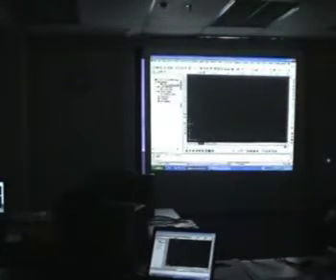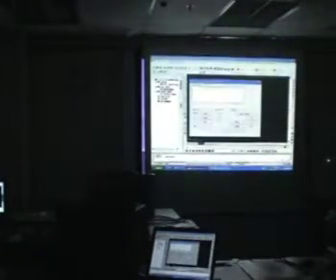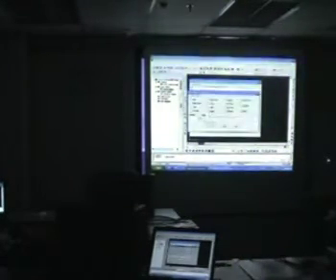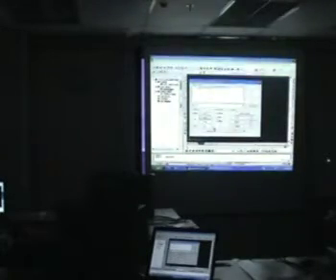And what I'm going to do is extract information from that drawing, because it's possible that drawing may have a lot of other garbage inside. Maybe you've got other contour lines, even other text like the words sekolah, rumah, that you don't want to put into your 3D points. So this is the use of query. We're going to use the current query. This is to basically filter out the information, to extract certain information from the attached drawing. I'm going to call out only the text values. That means only the text. If there are any lines or circles or blocks, they're going to be ignored. I only want to take the text.